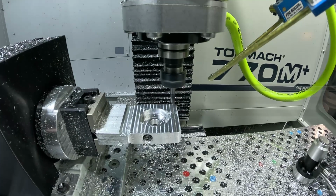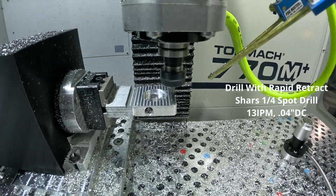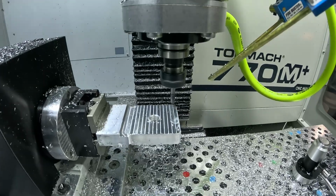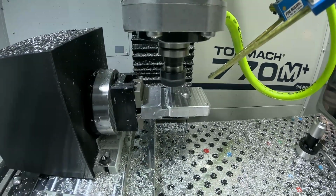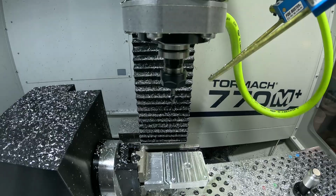Alright guys, now we're just going to do our spot drilling operations. I'm using a 1/4 inch carbide spot drill. So this cycle goes rather quickly. We spot our holes, we flip over, we spot the back side. Again, we're going down 40 thousandths from the top of the hole just to give us a nice chamfer. And now we transition into the drilling.